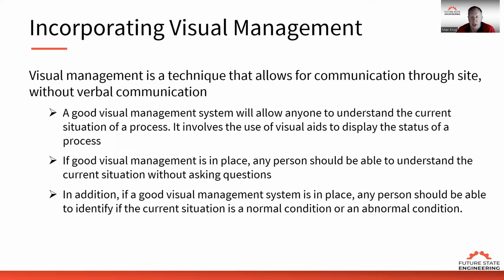Now we put visual aids in place to understand when the machine is not being loaded to full capacity. That andon light comes on and tells us that they're not loading to full capacity and it's not running at optimum efficiency, and we take immediate corrective action to correct the problem. In this case, we put a troubleshooting guide in place. If you see these conditions, these are the things you need to check first. So the operator is the first line of defense. He has an action item that he can take based on the condition. If he can't fix it, he immediately calls the supervisor. The supervisor comes over. He has a set of actions that he needs to do. And if that doesn't work, then we call maintenance, and it keeps getting elevated until the problem gets resolved.